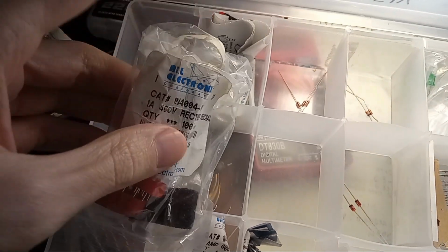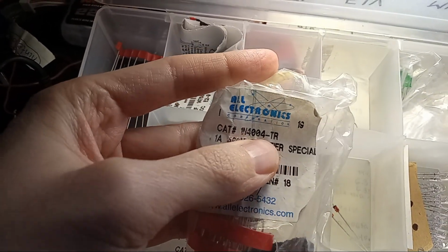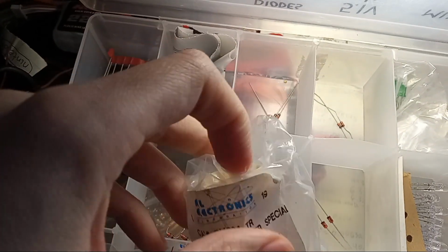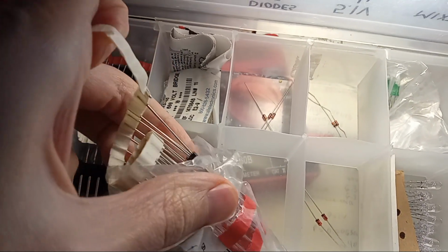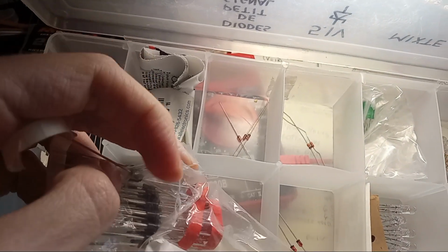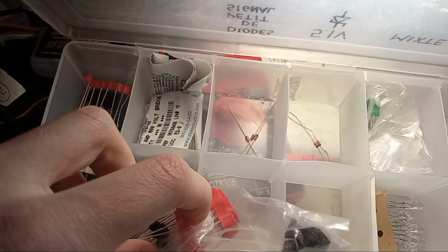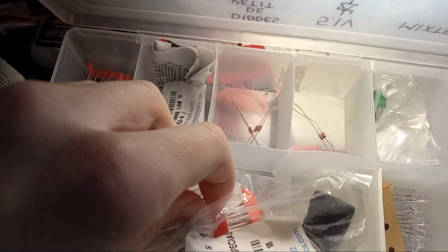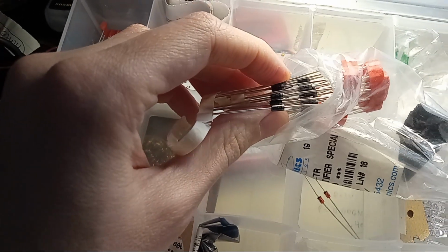A typical diode is the 1N4004. This is a rectifier rated for 1 amp, 400 volts. It'll block 400 volts, allegedly. Really, you should only run everything at half its rated voltage. This is, as mentioned previously, called derating.